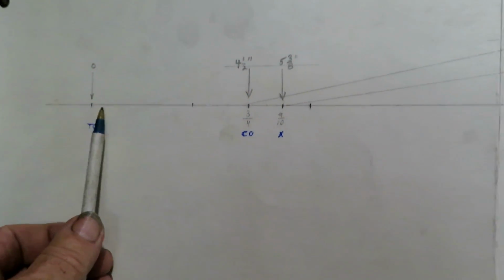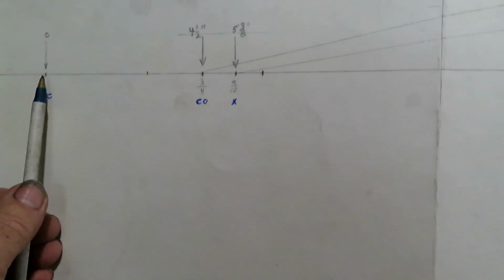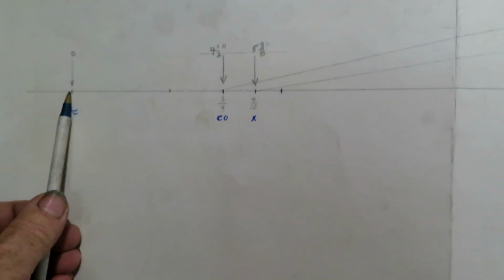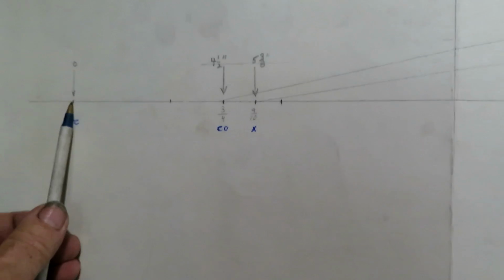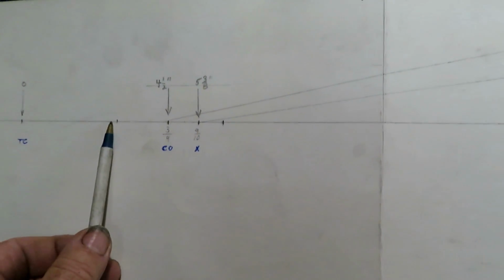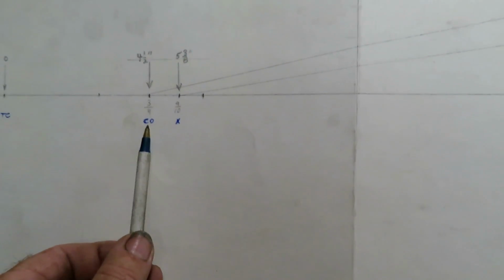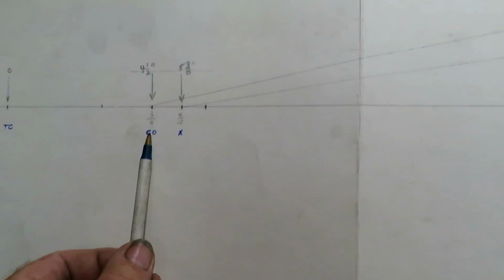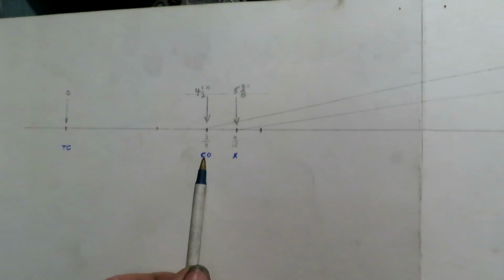So the first thing that I'm concerned with is the steam. Well, the steam admission will be a little bit before top dead center, and that little bit is called the lead, and I'll show you about that later. But the steam is being admitted and the piston is coming down, and when we get to right here, which is 3/4 of the stroke, or 4.5 inches down the stroke, it's the cutoff. That's the point at which I want the steam to cut off.